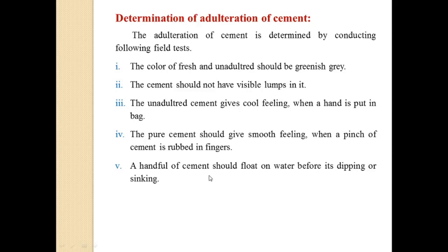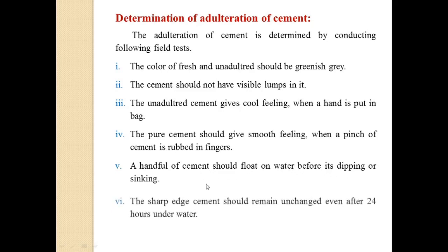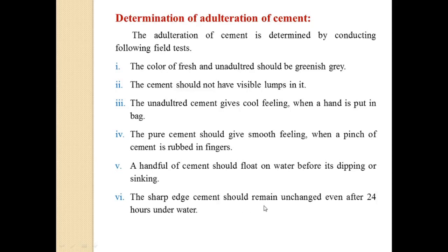That is, if we take a handful of cement and throw it on the surface of water, it should float for some time and then sink. Next, the sharp edge should remain unchanged even after 24 hours underwater. That is, we prepare a sharp-edged cement paste cake and put it under the water for 24 hours, and after 24 hours its shape or edges should not be changed. Okay, so it is unchanged.